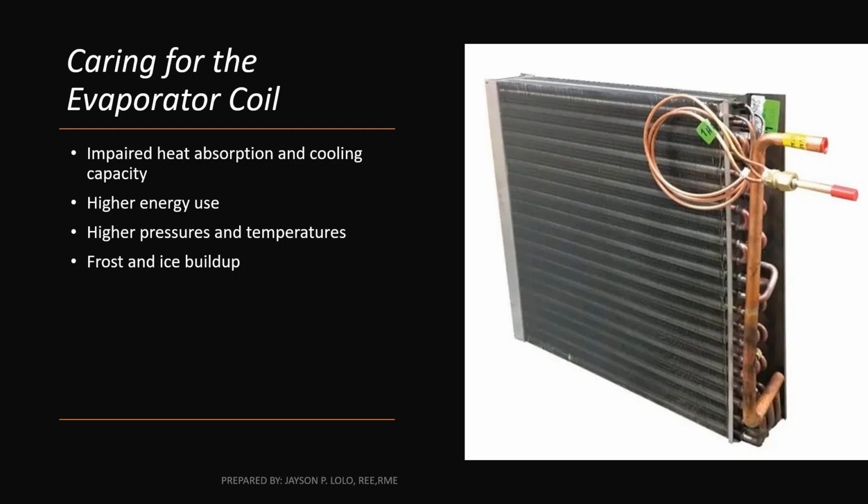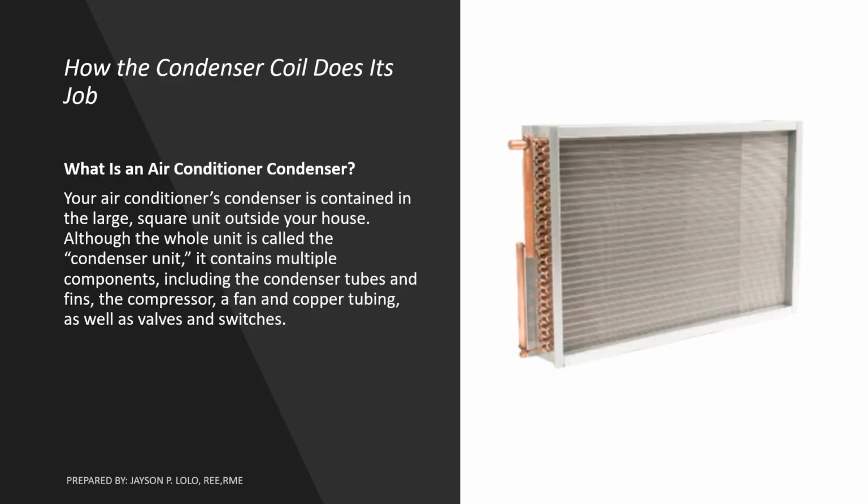The refrigerant running through a dirty evaporator coil doesn't warm up as much as it should. So this very cold refrigerant causes water vapor in your air to freeze rather than condense into liquid. So eventually the whole evaporator coil can frost over. So frost and ice build up.